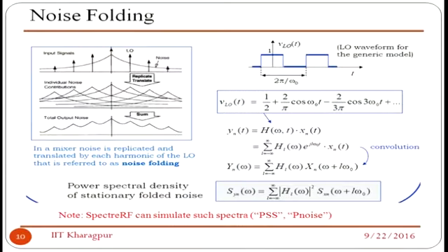You talked about 1/f noise, 1/f^(n-1), that is called 1/f squared, 1/f cube. How are these noises coming? All these noises are coming because of the concept called frequency folding. You call it pink noise. So I am giving you a very simple concept of how the noise is actually contributed from all the harmonics, because all are translating back to your desired frequency.